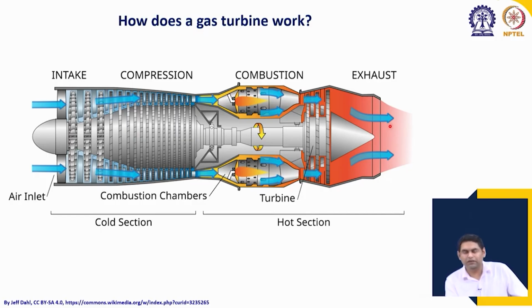So, jet engine working is a little bit different as compared to an industrial gas turbine. In an industrial gas turbine, we will have more stages of turbine, and more work will be created, and that extra work will be used for running the external load like generators. Whereas for jet engines, fewer turbines are required, because turbines are present just to run the compressor.